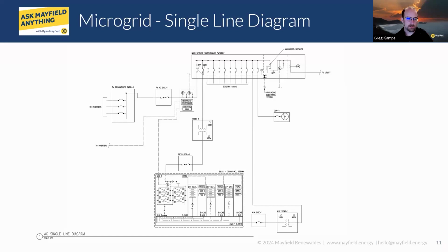So, going through some of the components, if you're just walking through it, you have the inverters over there. There are obviously modules coming into the inverters, and then they all tie together in a recombiner panel board. There's much more that is not being shown there, but that comes in as an AC being added into everything being combined, in this case, in the main switchboard.